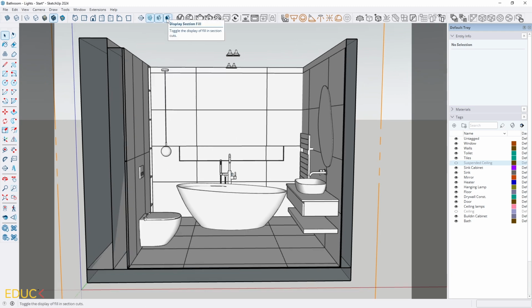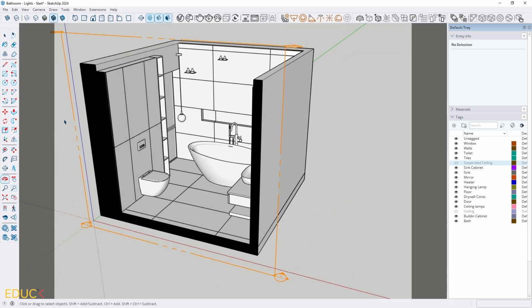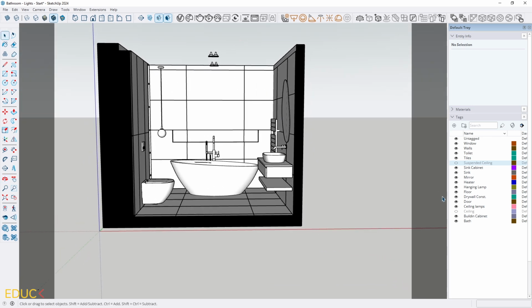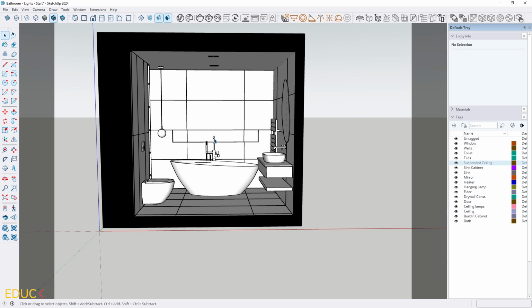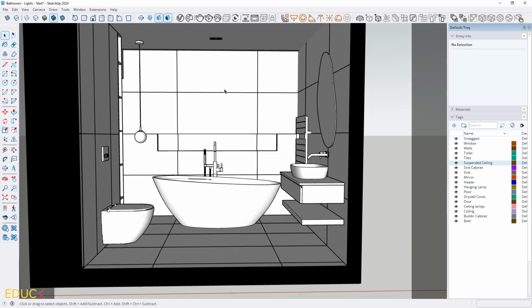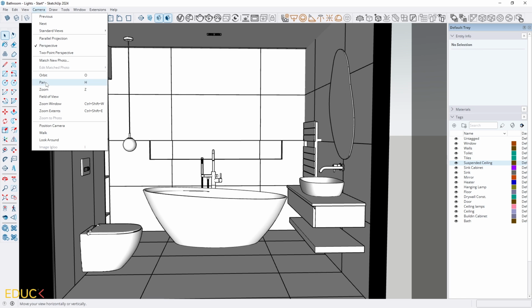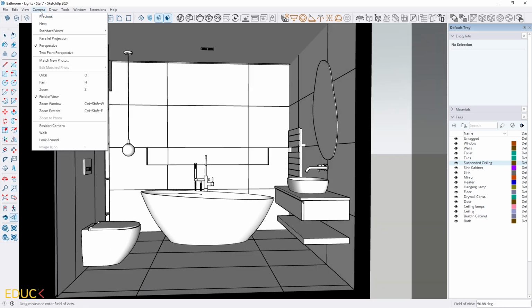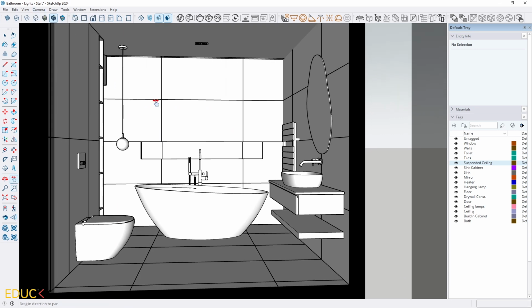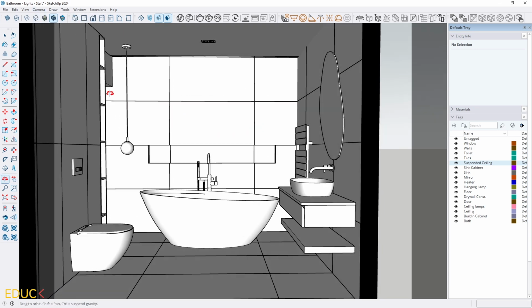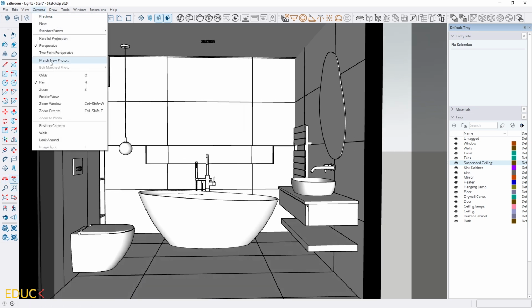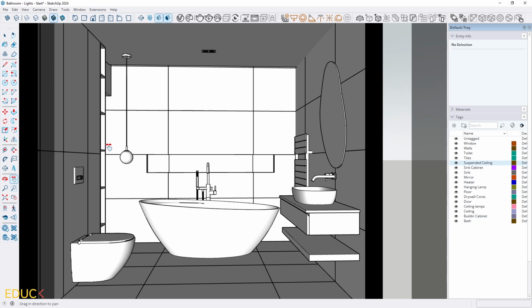And here I can check display section fill. And let's see that these walls are solid. And I uncheck this option, display section planes. It's not necessary. And then on the right side, I unhide ceiling and suspended ceiling tag, and we can create the view. Remember, when you are creating a view, it's good to change field of view, something like 50. Yeah, it's fine. And then I go to camera, two-point perspective, and it looks fine. We can change that. We need to find the best view. Later, with the final visualization, I will adjust this view again.